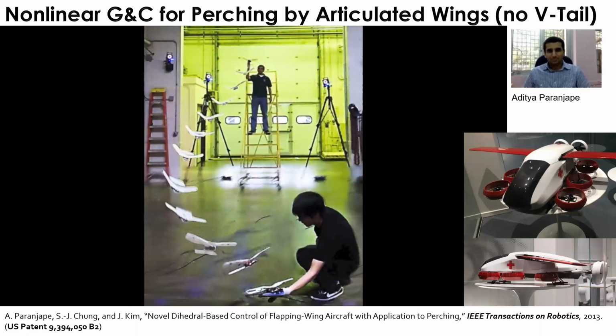And then when you add these multiple blocks of learning for motion planning and also feedback control, like the example I gave you, you have to ensure that this black box, or deep neural network, and oftentimes in the perception community you use a convolutional neural network, shouldn't destroy the stability of your estimation or learning system or feedback control, right? Oftentimes they are stochastic, in the sense that they might be governed by stochastic nonlinear dynamics or uncertainty in your state estimation. So estimating the stability of nonlinear stochastic dynamics is not a trivial matter. We have some tools for that.